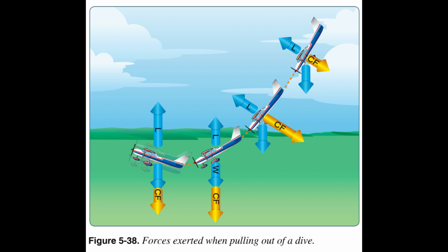In one design, the wing is twisted to a higher AOA at the wing root. Installing stall strips on the first 20 to 25% of the wing's leading edge is another method to introduce a stall prematurely. The wing never completely stops producing lift in a stalled condition. If it did, the aircraft would fall to the earth. Most training aircraft are designed for the nose of the aircraft to drop during a stall, reducing the AOA and unstalling the wing. The nose-down tendency is due to the CL being aft of the CG.